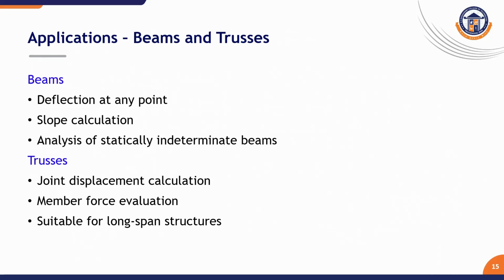So, the applications of strain energy in beams and trusses. Energy principles are widely applied in deflections of beams, slope calculations, joint displacements in trusses, and analysis of long span structures. In many cases, energy methods are simpler and more elegant than the force method.